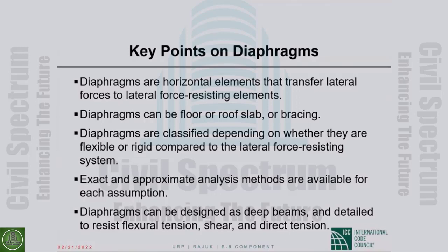Exact and approximate analysis methods are available for each assumption, meaning whether you assume flexible diaphragm or rigid diaphragm. And then diaphragms can be designed as deep beams and detailed to resist flexural tension, shear, and it could even be direct tension.